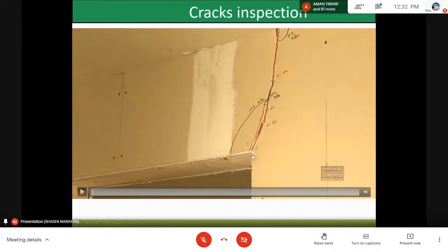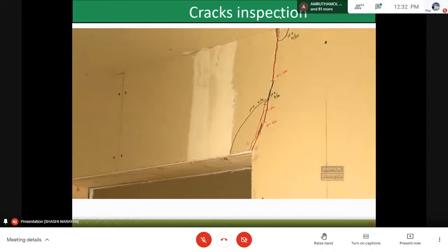You would have read that the cracks will always start from the openings and then go onward. So when we have masonry construction, then you go with the reinforcement at the openings. If it is a framed structure, generally we do not, and in that case during an earthquake a non-structural crack is developed.